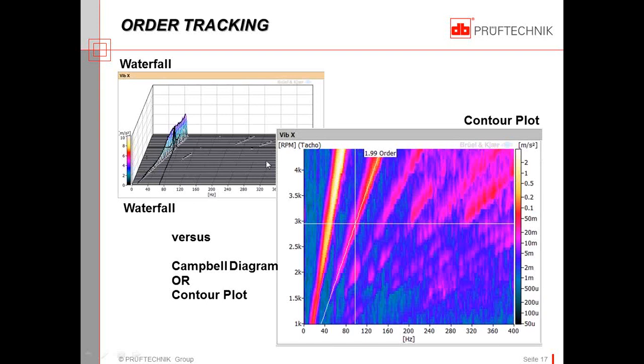origin. And as each one of the harmonics, starting with the highest harmonic, coasts down and goes through an area of resonance, it excites it. And then the first, the second, the third, and the fourth all get excited. So that's typically the plotting technique that we use for frequency spectra as a function of RPM.